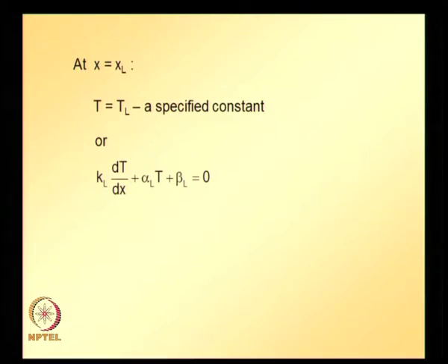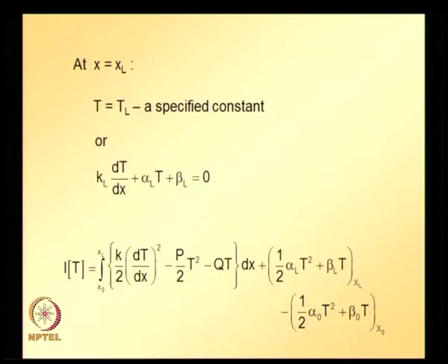So what we did is we applied the Rayleigh-Ritz method, and we found the equivalent functional before we proceeded and substituted finite element approximations in terms of a two node linear element, finite element approximation of T and derivative of T. The equivalent functional that we obtained in the last class using the Rayleigh-Ritz method is given here, and then we substituted finite element approximations of T and also derivative of T, and we have taken a two node linear element.